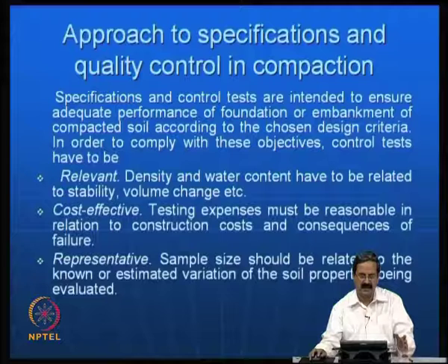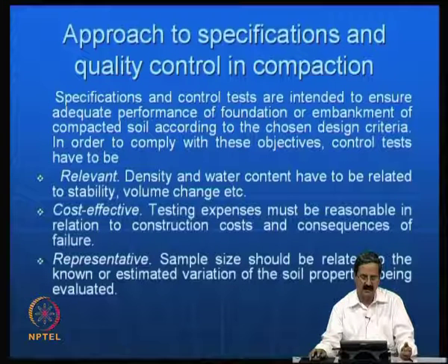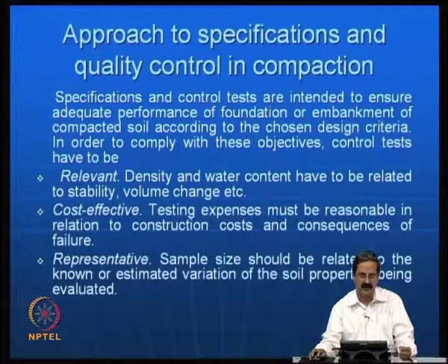If this strength criterion is met by adhering to this density and water content, then the job is done. The same applies to volume change, in which we need a specific density and do not want a lot of settlement or volume change. So the specification should be relevant to what you are interested in.